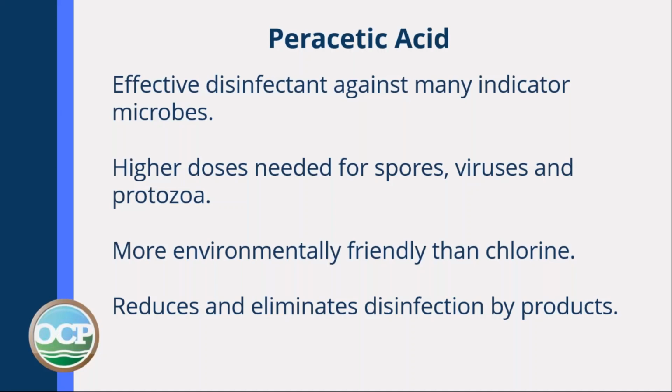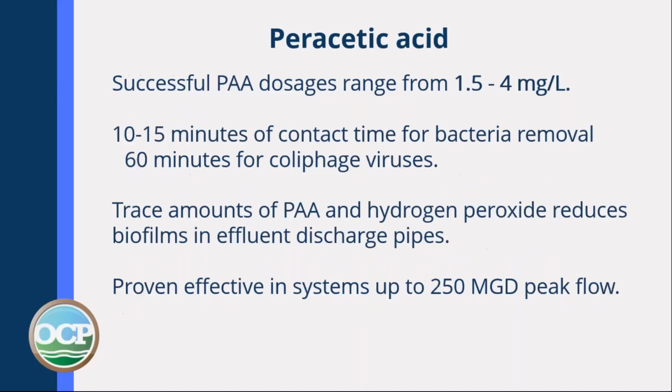There's nothing that has to be removed from the water after you add PAA. It reduces and eliminates disinfection byproducts. Successful PAA dosages range from 1.5 to 4 milligrams per liter. 10 to 15 minutes of contact time is needed for bacteria removal. 60 minutes is the time it takes to remove the coliphage viruses.